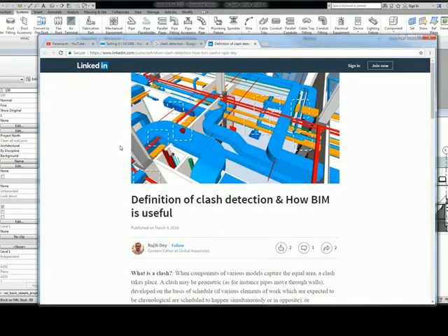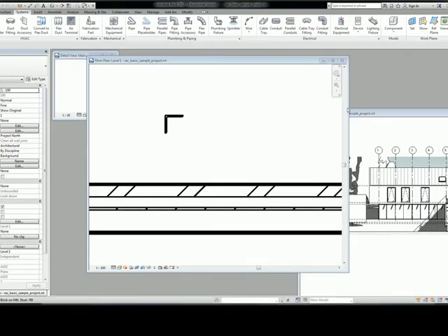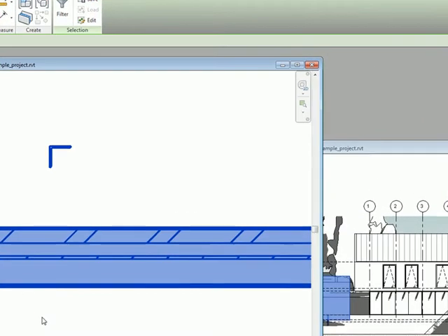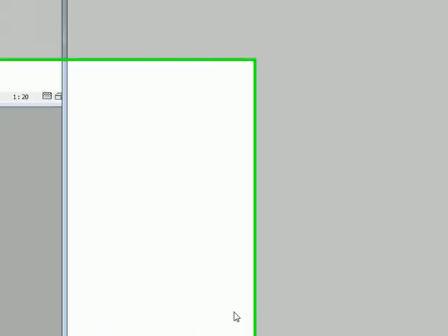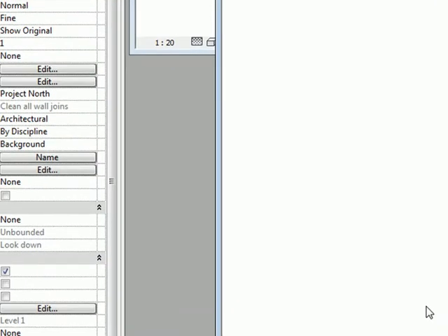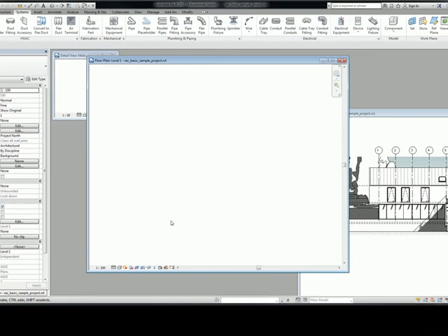Well, we won't be doing clash detection, but the reason I want you guys to have a certain respect and affinity for all the other disciplines modeling their stuff too, and the accuracy of modeling, is because of stuff like that. You'll get there in your career, I promise. Is that another plugin? Yeah, so basically the Revit models, like your model, your consultant models, they all get put into the software, and then it just runs one model versus the other, and it tests whether or not they're coincident. What's it called? Clash detection.